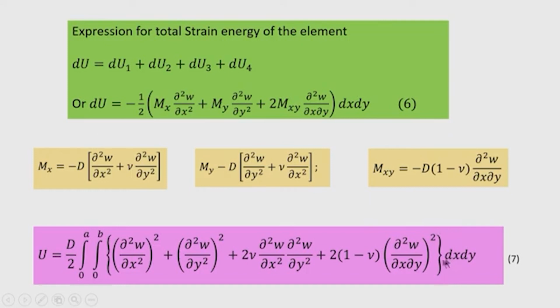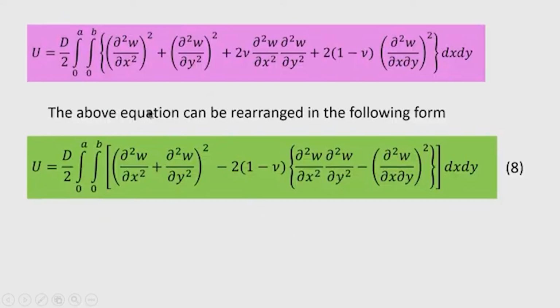This is the most useful expression for solving the plate problem, because solving the plate problem using the Rayleigh method or approximation or any other Galerkin method requires a first approximation of the deflection. Therefore, this form of the strain energy is very convenient to be used for plate problems. Okay. Now, this expression can be written in another way, a very convenient form, from which some physical interpretation can be done and the strain energy expression can be simplified for some cases.